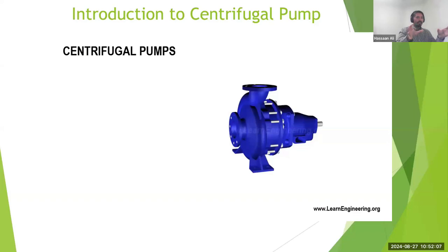You can actually have a multi-stage pump for pumping in this kind of application. And usually you would need a multi-stage pump because, as I mentioned earlier, the pressure of the pump depends upon your rotational speed and also the size of your impeller, right? You can increase your rotational speed to a certain point. You cannot go beyond that, right? For example, if your motor can deliver like 3,500 RPM, you can only go to 3,500 RPM. You won't be able to get any pressure more than that because you cannot rotate it any faster. In that case, you have to use a multi-stage pump.